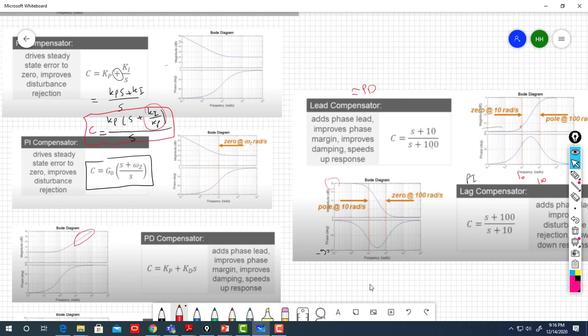But also the PI controller is not as good as the lead compensator in energy or computational efficiency. But now, because of speed-up in memory and calculation, we can easily integrate an integrator, a PI controller.